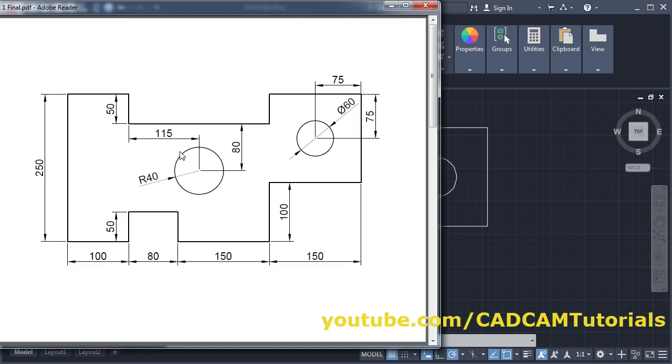Then next is circle of radius 40 at the distance of 80 from this horizontal line and at the distance of 115 from this vertical line. Now this total length is 150 plus 80, that is 230. That means this 115 is half of this 230. So what we will do, we'll just track this midpoint and give the length of 80.